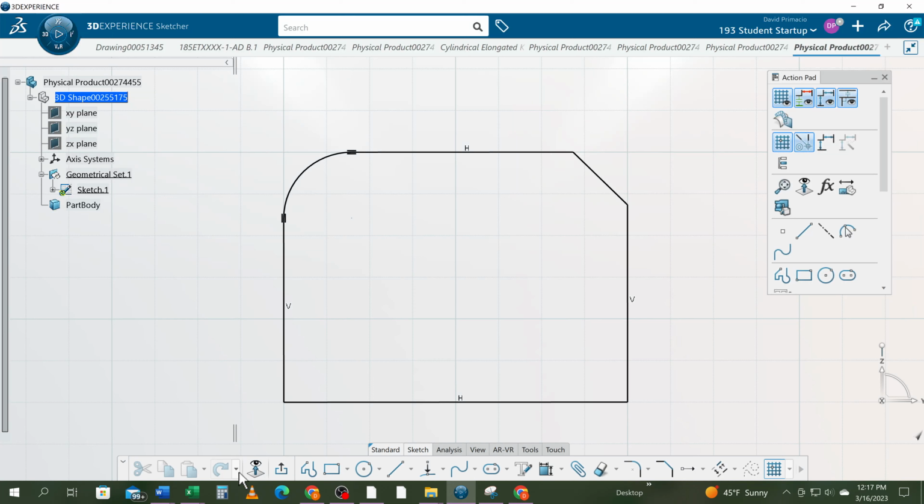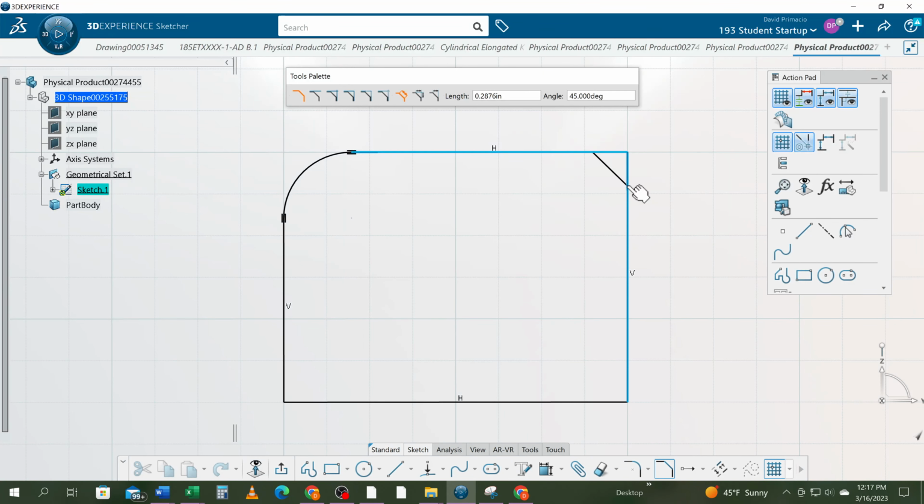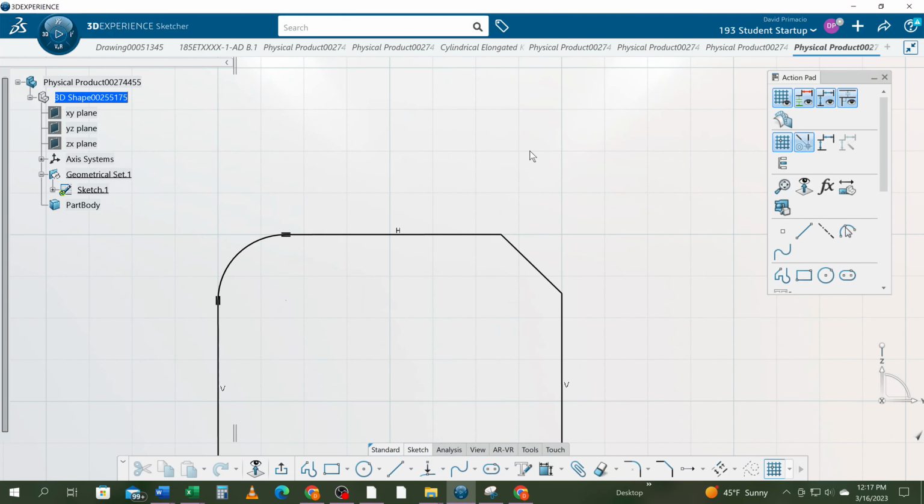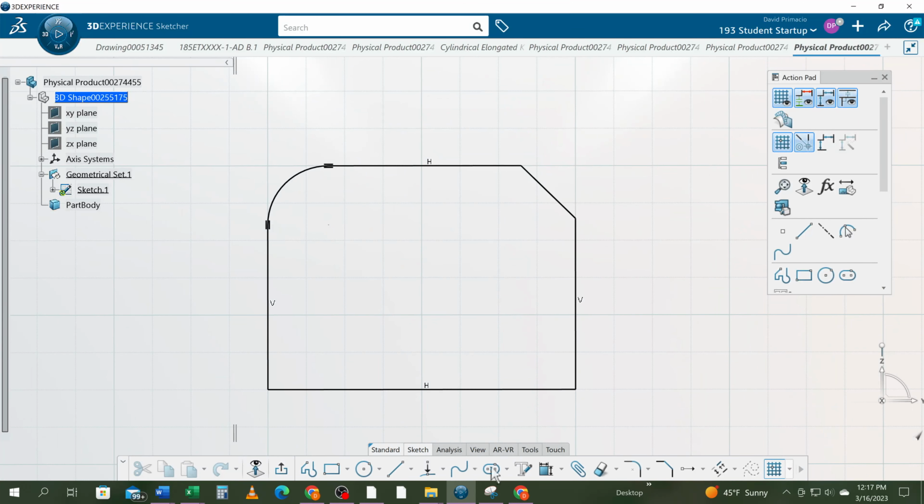if you want that to be a specific length, I'm going to hit undo, Control Z, and go back to chamfer. Select this line and this line. You do have the option for a length. Now you notice that if I come over here and I try and type in the length, 1/2 inch, sometimes it doesn't do that. It goes on the opposite side up towards the top or something weird. And it is a 1/2 inch length line. The hypotenuse of this is a 1/2 inch.